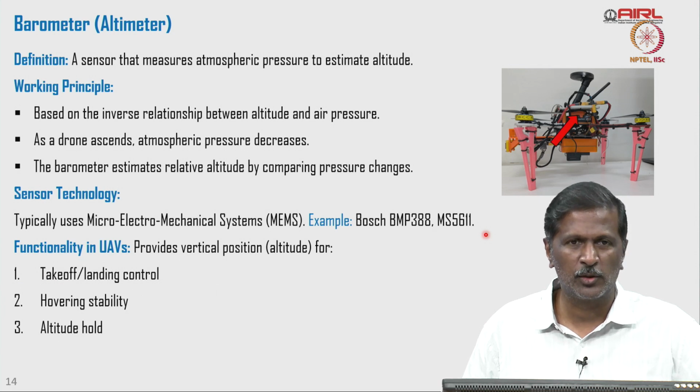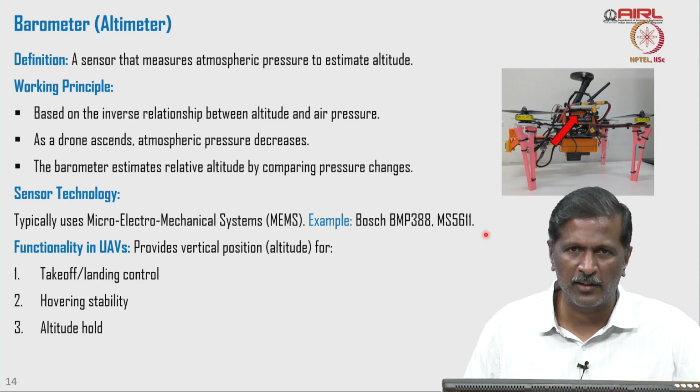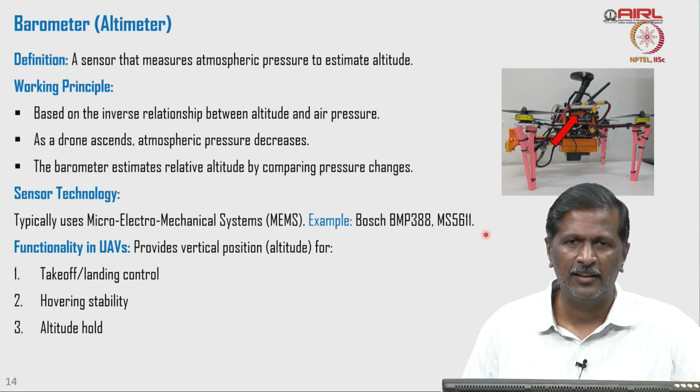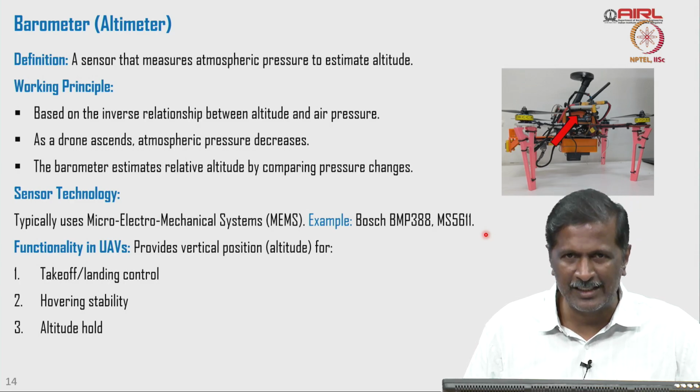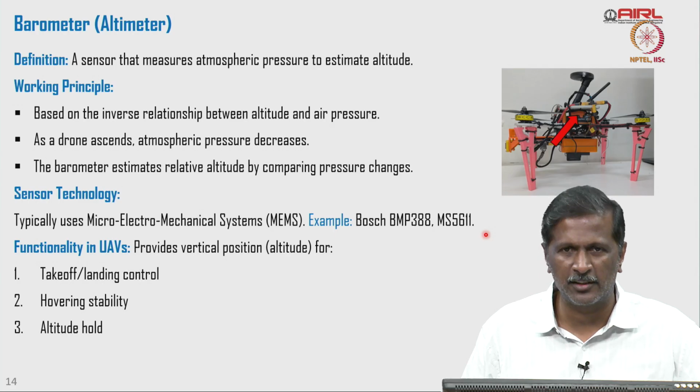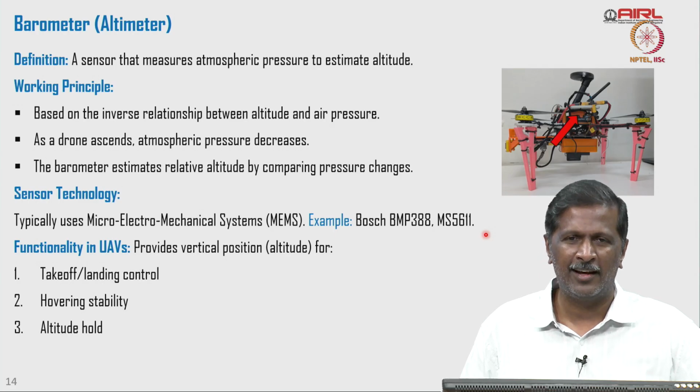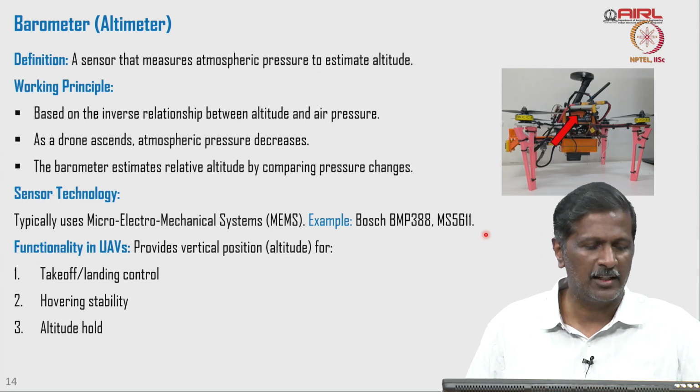What is it useful for? It is useful for your takeoff and landing. You want to take off from the ground, go to a specific altitude and hover, or land precisely at a particular point. I mean, for a point you need XY measurements, but for the rate at which you want to descend to come to the ground, you need this altimeter.